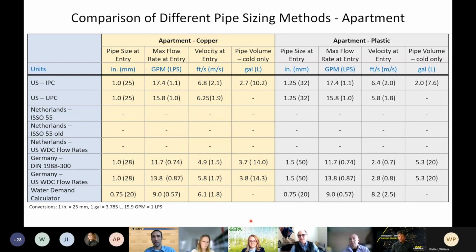So we pushed the 8 feet per second for cold and 5 feet per second for hot, for what copper recommends, but also the higher the velocity we can get, the more likely we are to scour that pipe and keep it clean of biofilms, which can seed on the side of the pipe and breed the bacteria and waterborne pathogens that we know is a reality in our world.